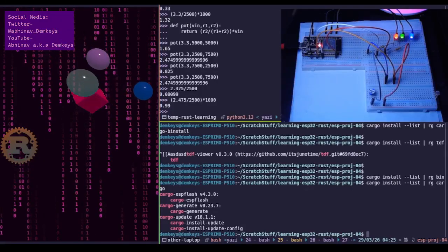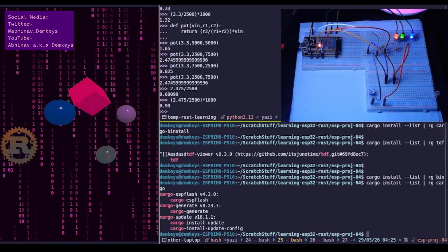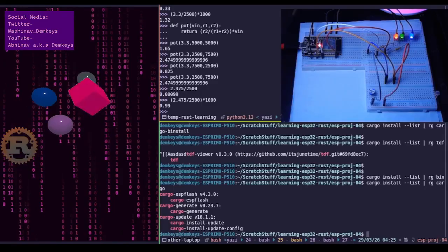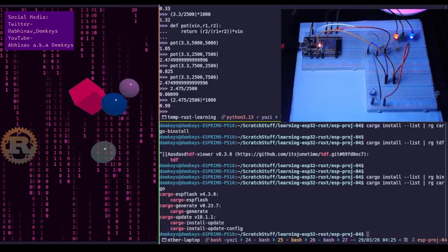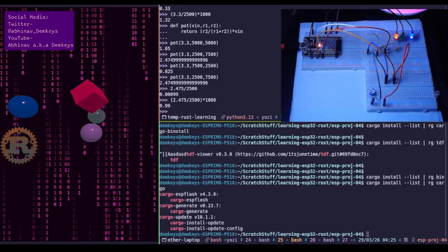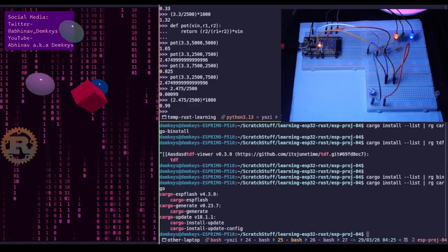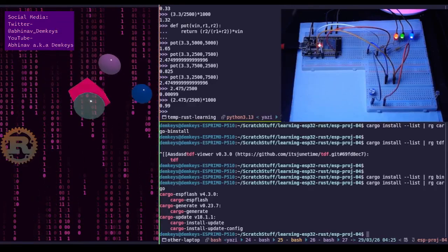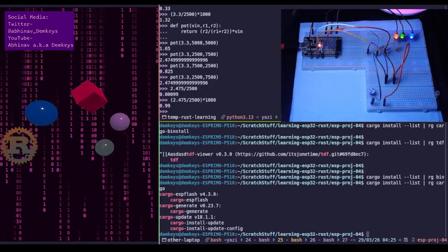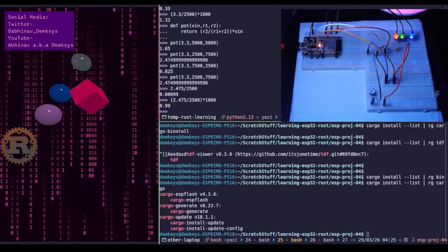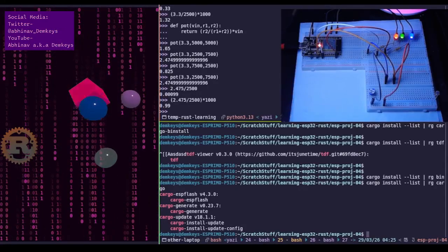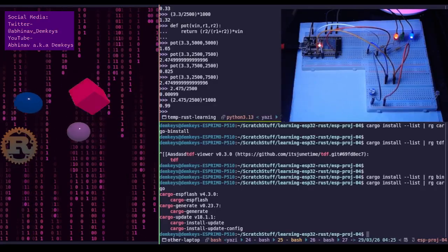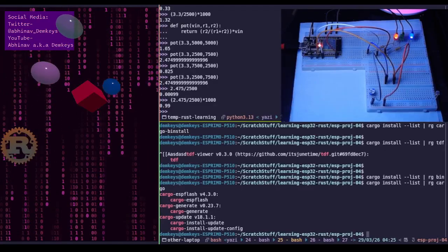Sorry, zoned out. Okay. Then ESP Flash. ESP Flash is a serial flasher utility based on esptool.py for Espressif SOCs and modules. This will be the tool used when we are not using probe-rs to put our code into the device and run it. Okay, if you encounter any problems, you can try installing the exact version used when this book was written. Okay, all right, great.